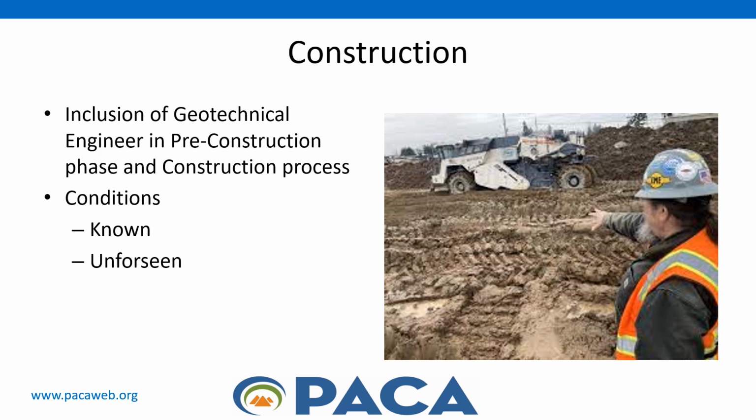Now, keep in mind that there are always two paths which can be taken to use cement to improve the subgrade soil. When marginal conditions are foreseen before the construction begins and sufficient time is available for adequate field testing and laboratory testing, the cement soil stabilization application is considered to be on the design path. Although, when unforeseen marginal conditions are encountered during the construction process and an immediate solution is required, cement-based mitigation can be expedited with engineering judgment, previous experience, or an abbreviated laboratory and testing program.